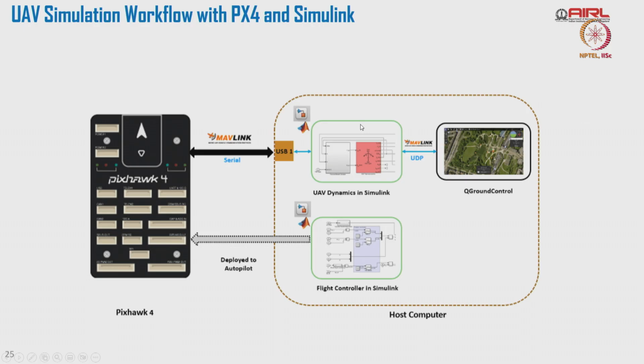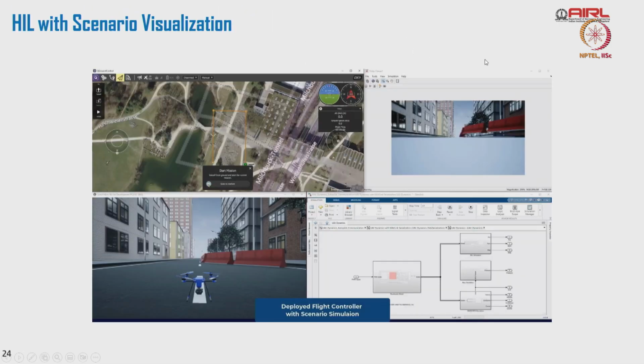There you can verify even the PWM command coming from your PX4, whether it is driving the motor properly, and whether you are getting the thrust on a thrust bench. It is possible. So this setup will help you visualize and analyze the performance of the flight control architecture that you are building, and also the mission plan that you have made, whether the specific drone is capable of executing the mission, and what the deviation in the mission performance is. All that can be evaluated easily with this UAV simulation workflow with PX4 and Simulink, right.